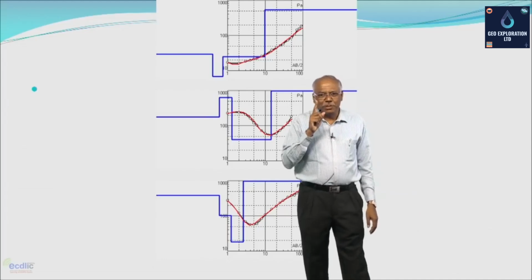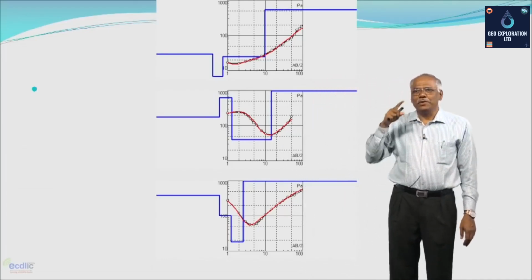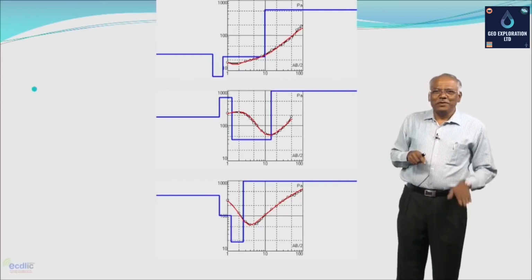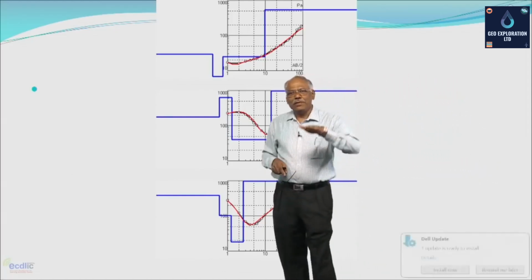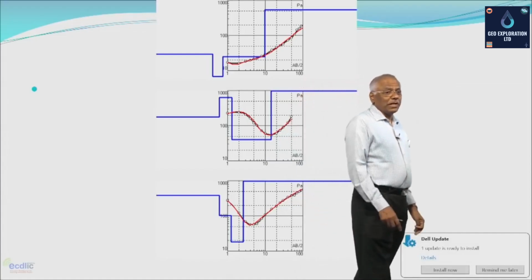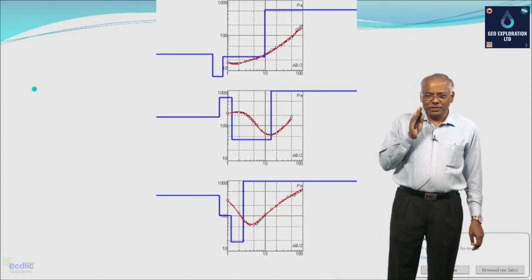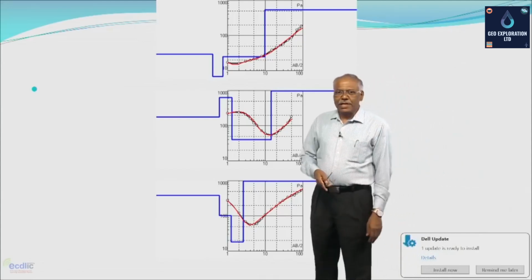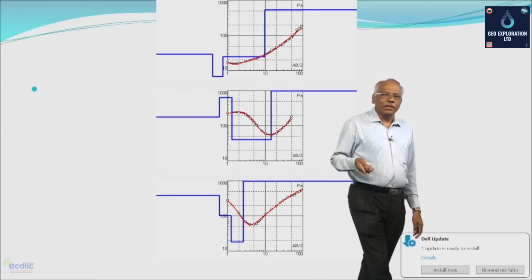This bell type curve indicates that rho 1 is less than rho 2 is greater than rho 3, and therefore, you will have low resistivity for the third, deeper layer, but high resistivity for the middle layer. It means that at a deeper level, you could get low resistivity, which will indicate the possibility of groundwater, and that is something you can interpret with the help of these types of curve, which is typically done by matching the field curve with the theoretical curve.